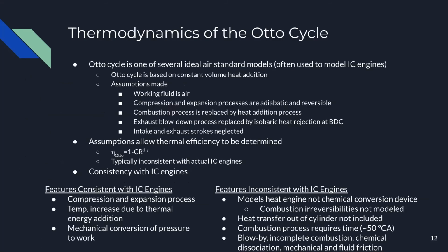So next I'll be discussing the Otto cycle, which is one of several ideal air standard models available. The Otto cycle is typically used to model IC engines and is based on a constant volume heat addition process to replace the combustion process. A couple assumptions that are made for the Otto cycle are that the working fluid is air, and the compression and expansion processes are adiabatic and reversible.